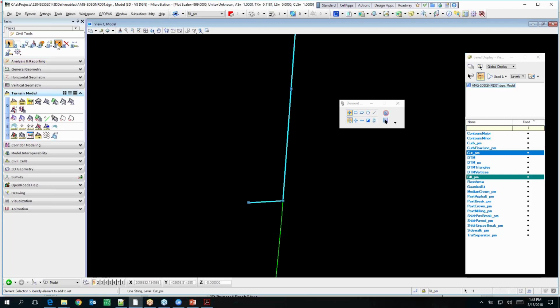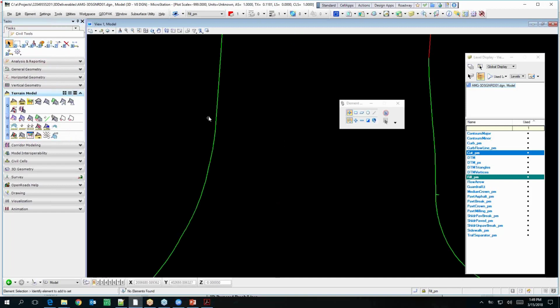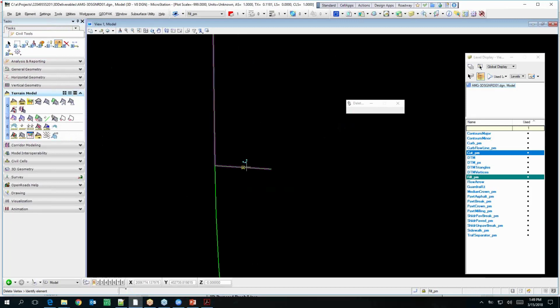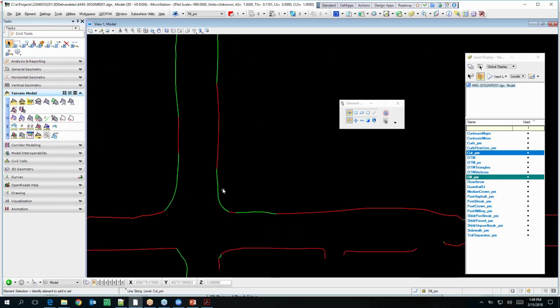All right, let's do that then. Just delete that one vertex. Kind of just did delete vertex. Yep. Oh, there we go. We clean that up. This one's got the same problem, and this is where this corridor was clipped, so I can see why that's happening. I don't know if there's a way to clean that particular issue up in the model though, because it's already clipped there.